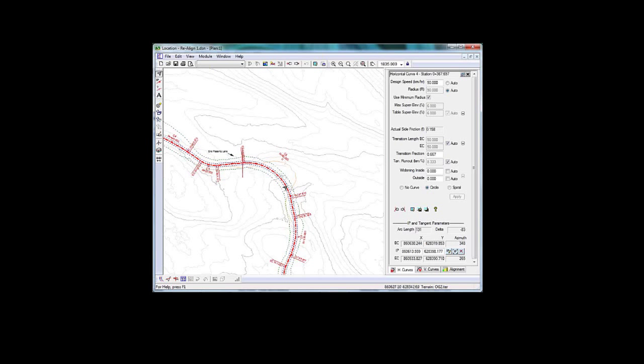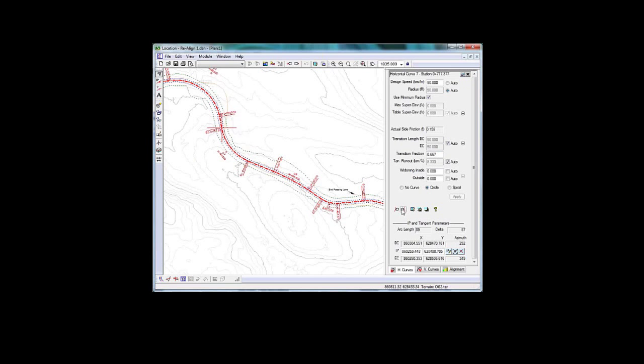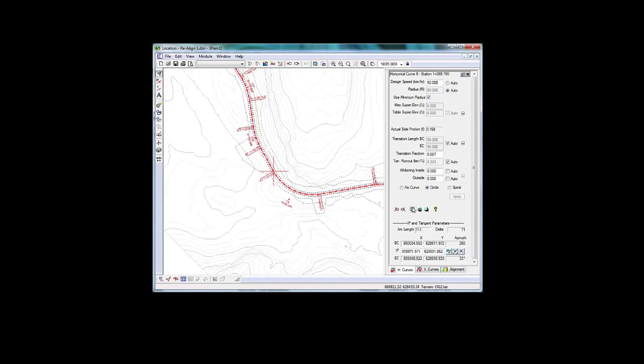And that still produces a curve that there's no way we can track the logging road. But then further along, I was able to put in curves with 60 kilometers per hour, like this one here, and I was able to track fairly close to the old logging road. And then in this area, here's the cross section. You can see the old logging road profile there. In this section, I moved over a little bit because I didn't want to go up this, cause a lot of rock cut in the hill here.